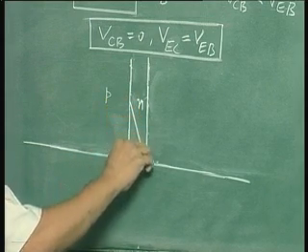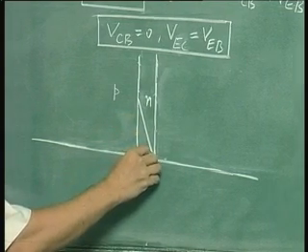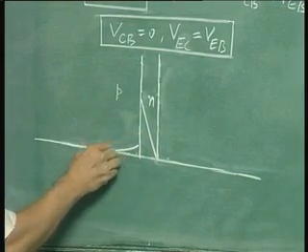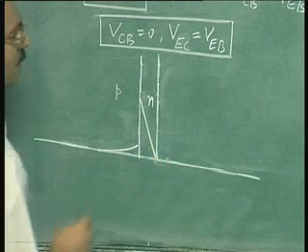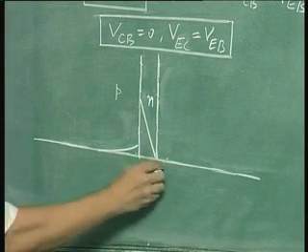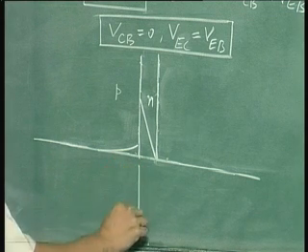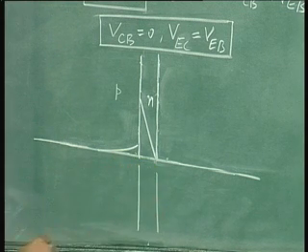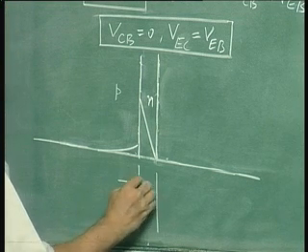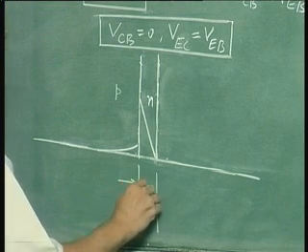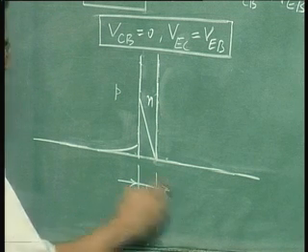So you have this excess carrier distribution in the base, then you have this for your emitter, and you don't have any excess carrier concentration in the collector because the collector base voltage is 0. So in this case we have already drawn the flow diagram. You have holes being injected from emitter to base, a small part of them recombine and then remaining get injected into the base, into the collector.